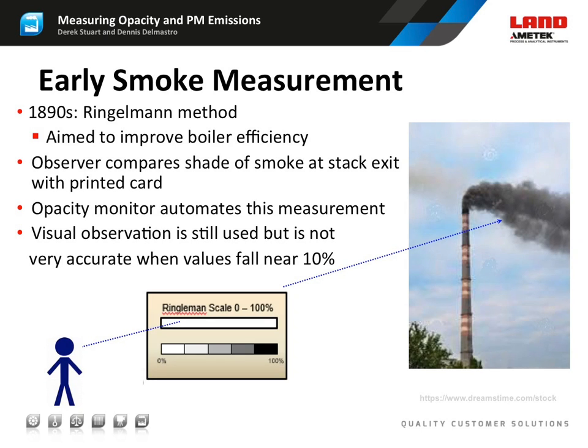In the very earliest days of the Industrial Revolution in America, individuals began to look at smoke coming out of their chimneys and tried to make an educated guess of how efficient their boilers were operating. A scale called the Ringelmann scale was devised to assist the smoke reader with his visible emissions.